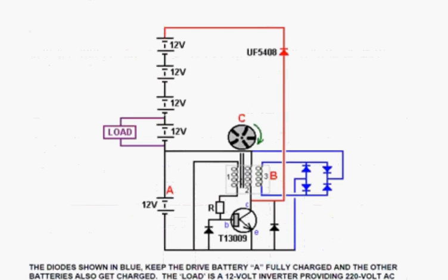Now, he started off with this circuit. He built a rotor, and in the rotor he put magnets, and the magnets spin round past a coil which has got a metal core. As it goes past, it powers the coils. It feeds, like the Joule Thief, the current to the base of the transistor, which drops the resistance between the collector and emitter to 0, which drives a strong current through coil number 2 and powers up coil number 3 as well.